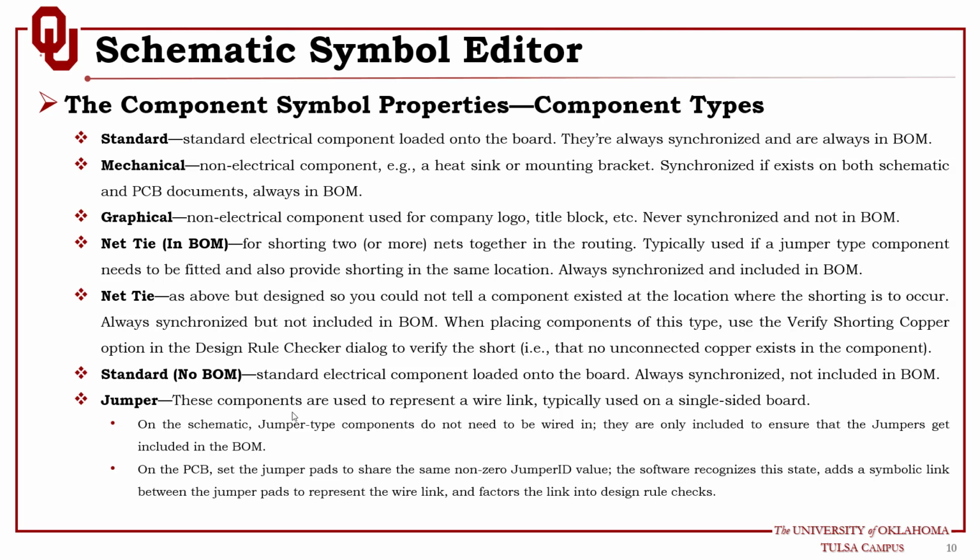So instead of making, let's say, 10,000 of PCB-A and 10,000 of PCB-B, if you can make one PCB that can work for both, where the difference is the assembled component, you will save a lot. Now you can make 2,000 of the same board, and you can save 15 to 20% of the cost. So jumpers, basically it's a jumper, and these are the old style.